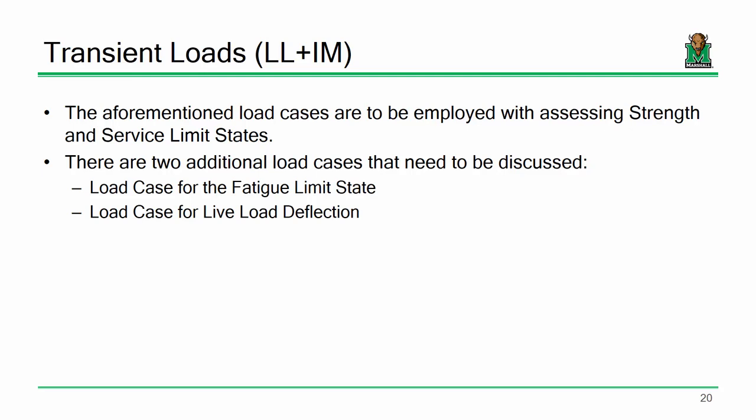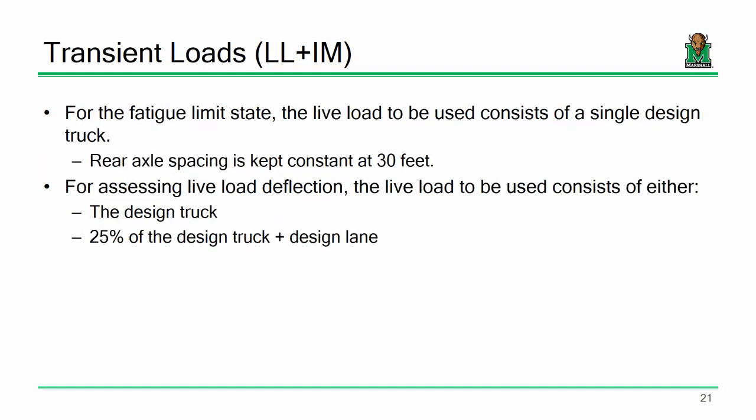What I talked about before was the strength limit state and the service limit state. If we are talking about fatigue or deflections, a couple things. So fatigue, like I said, we keep that rear axle spacing at 30 feet. It just goes off the way the fatigue spec has been developed. So if you look at what a computer program will output for truck moments or fatigue truck moments, they're pretty close, but fatigue moments tend to be a tad bit less.